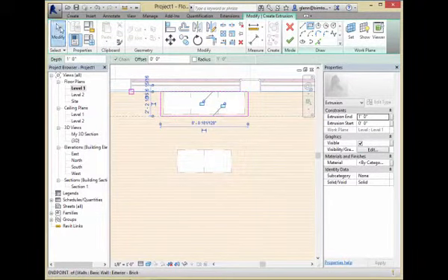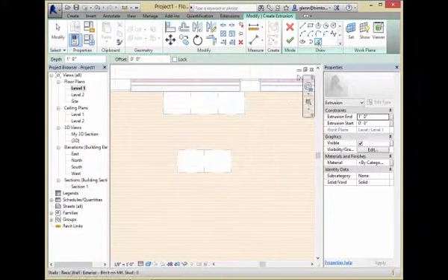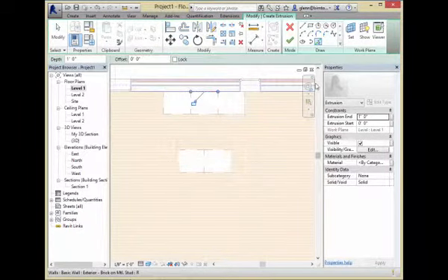Now, as you're designing, let me take that one out. You might want to actually use some picks and offsets to give you a little more control. What I actually tend to do is I'll draw that back line. Countertops can have a funny property. What they tend to do is actually follow the edge of the cabinets. And you give about like an inch overhang, so a little bit of overhang around the outside. So if I want to model that, another way to do that is to sort of say an offset of 0,1 and just pick the edges. This is a way just to get a little bit of overhang.